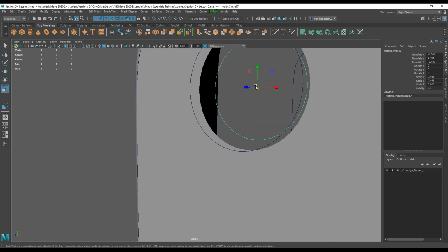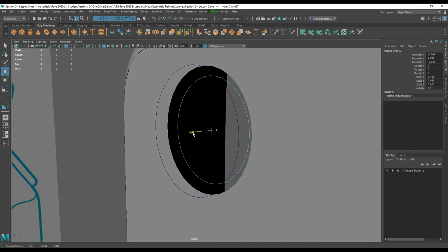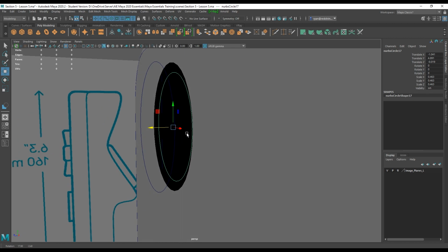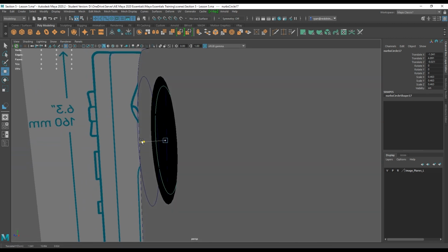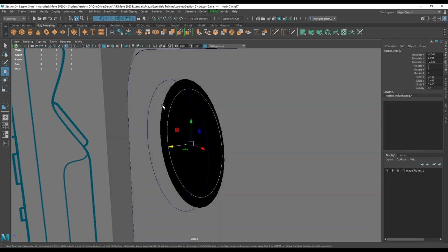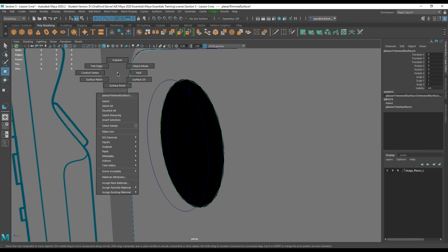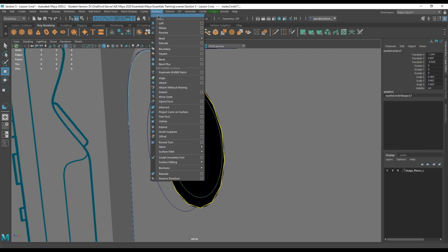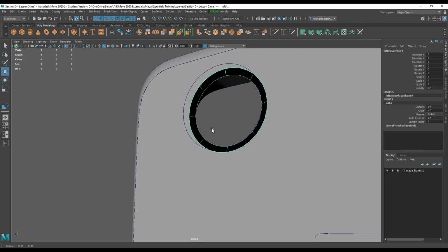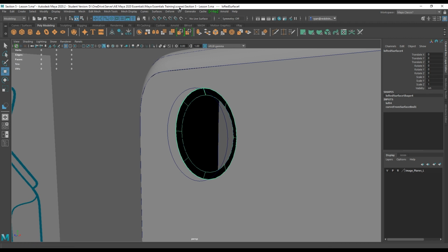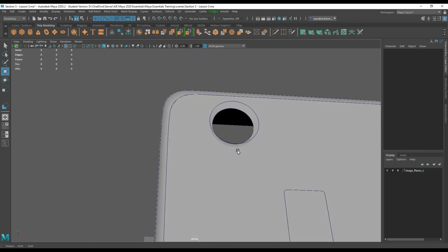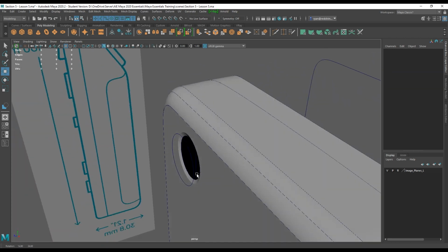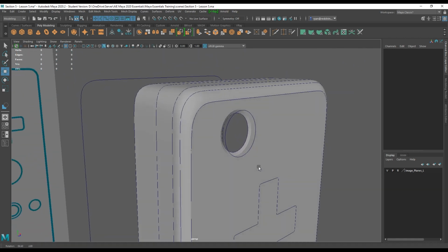Now in here I would take this guy and pull a bit forward so that I can get that bevel depth that I can see. So from here to here, I can select the curve on the surface that has been projected. I'm going to right click, trim edge, select that inner edge, select that curve, and we should be able to do a loft, which is great. That surface is backwards, so I'm going to go to surfaces, reverse surface direction. As you can see, we got a nice, sharp, clean bevel into that surface.